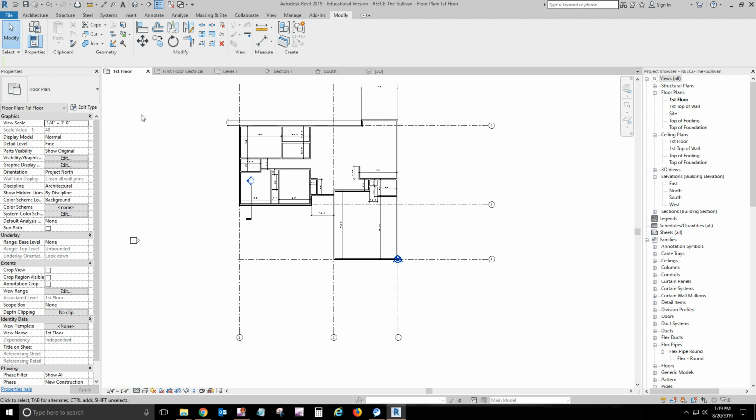To clarify, all design projects should start with the architectural template. If you're doing a construction management project, which we're not going to do in these classes, the construction template is just that. It's for construction management, not for architectural design. Okay, so we'll pop those in and edit those families so they reflect what we've got in our project here.